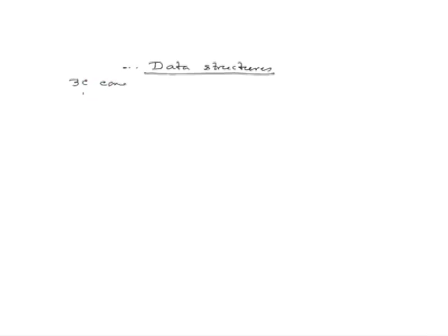So the BC conditions, we have primarily 3 types: Dirichlet, and we should use an integer code for it. Suppose we use code 0 for Dirichlet boundary condition, and what data we need: specified temperature, let's call that or denote that by TB.